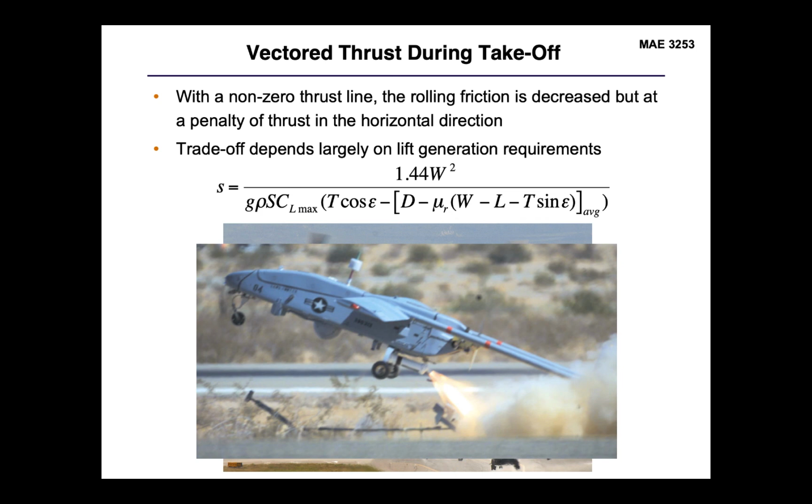You can also, of course, apply additional systems on your aircraft, such as rocket-assisted takeoff, with the most important thing to keep in mind when you start to do something like this being to make sure that the thrust line is acting through the center of gravity of your aircraft, or if it isn't, that you're able to overcome that moment with no dynamic pressure acting on your control surfaces, because you will be starting off at zero velocity.